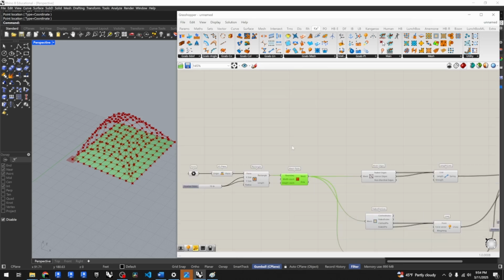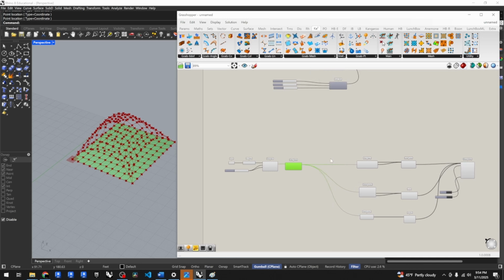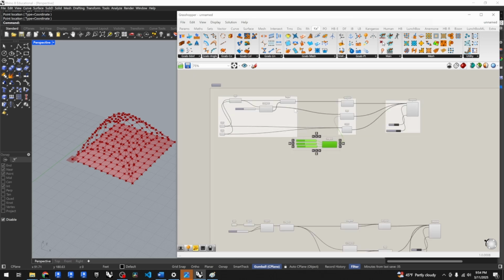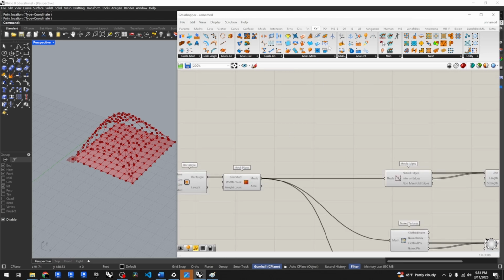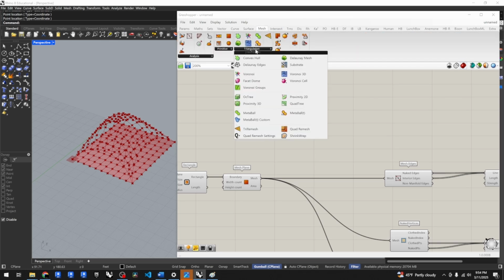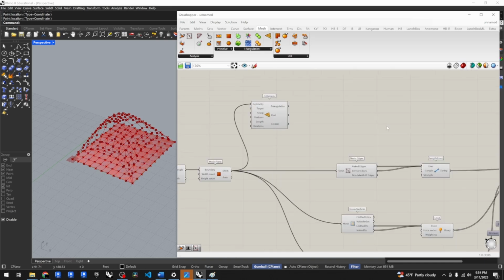So we have our mesh plane, and I'm going to hold the Alt key and just slide this over for a little bit more room. Unfortunately, I grabbed my vector XYZ up here. I'll just bring them in. And what I want to do, if I come into my mesh tab, there is a triangulation tool. And what I can do is I can say try remesh for a triangular remesh. I'll bring in my geometry, and I now have a triangulated mesh up here.